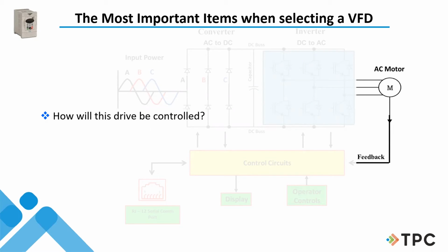Maybe flow, water flow. There's just all kinds of things. Pressure can do it. So, what do you want it to do? I mean, a lot of HVAC units now, the fans are VFDs, and they're controlling those fans. So they speed them up very slowly to start up, and much more quietly, and they can control things better with a VFD. So, how are you going to do it? What is it that's going to drive it or control the speed of it? Because you've got to know if it's something beside the potentiometer right next to the stop start button, you better know what it is.